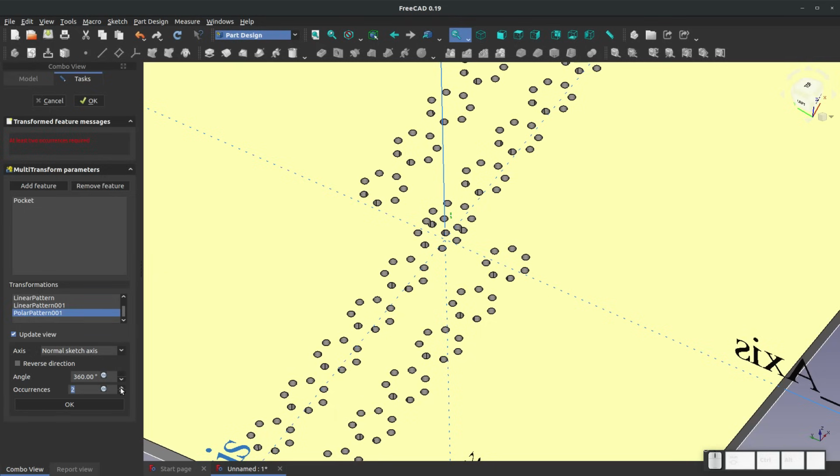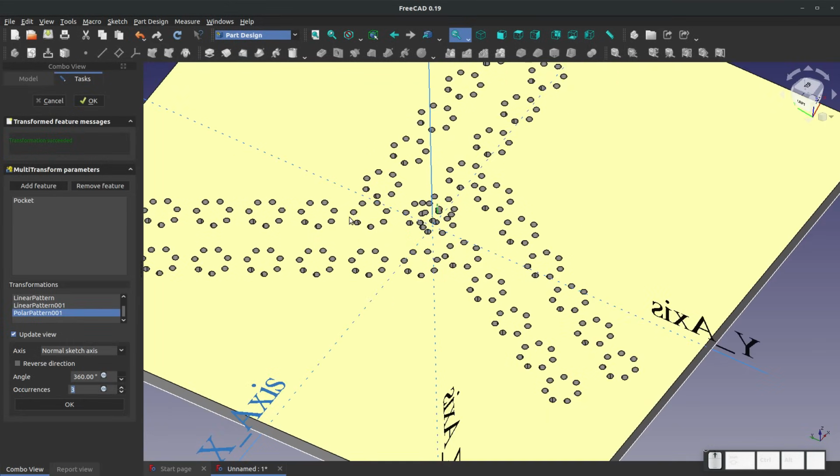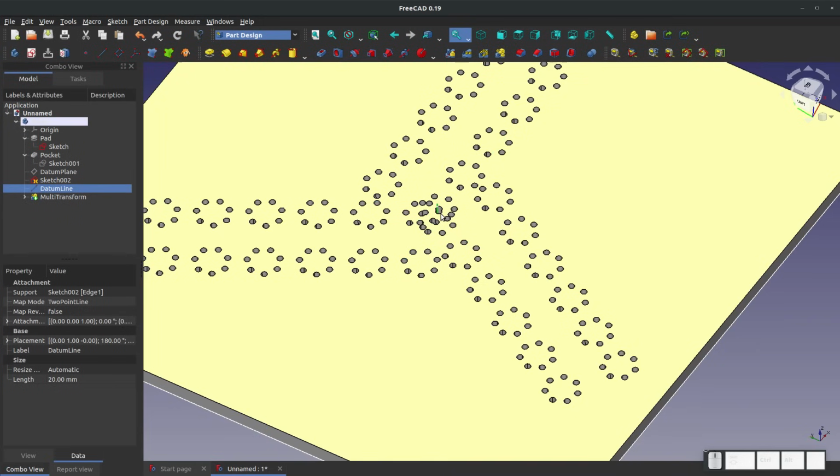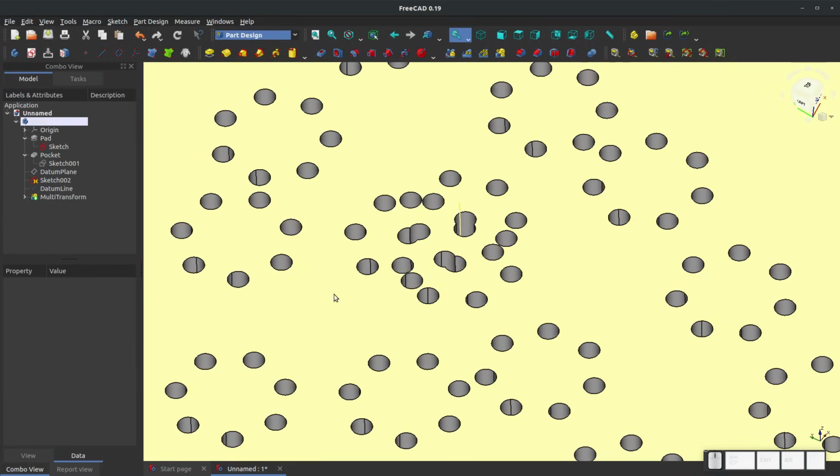Because, you know, it's overlapping and everything, but I think this goes to show the kinds of varieties of things that you can do with just one hole, if done right in FreeCAD. So depending on your hardware, that could take a long time, but there's an example of kind of a messy in the middle pattern that we made. I'm going to say OK to accept that. And as it's thinking about making that into actuality, patterns are heavy, but you can do a lot of patterning in FreeCAD. And there it brought it into actuality. So again, depending on your computer hardware, that could have gotten kind of computationally heavy. I'll go ahead and save that as a pattern example, despite how sloppy that is in the center.